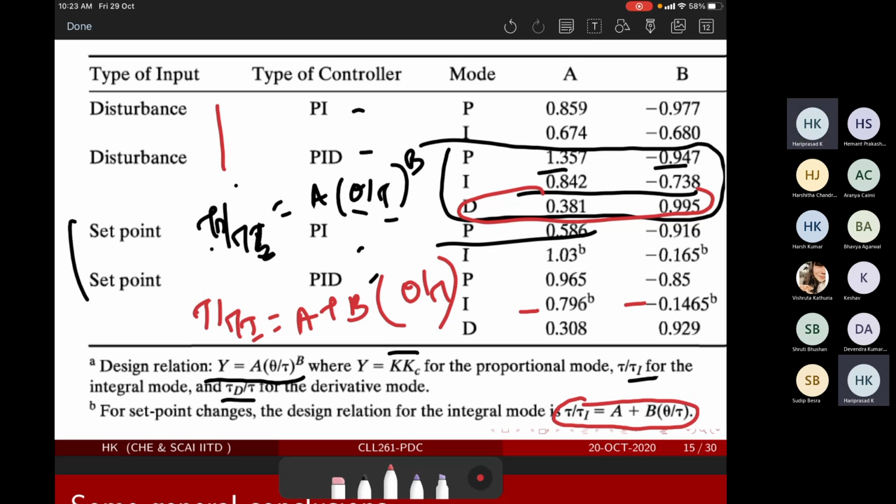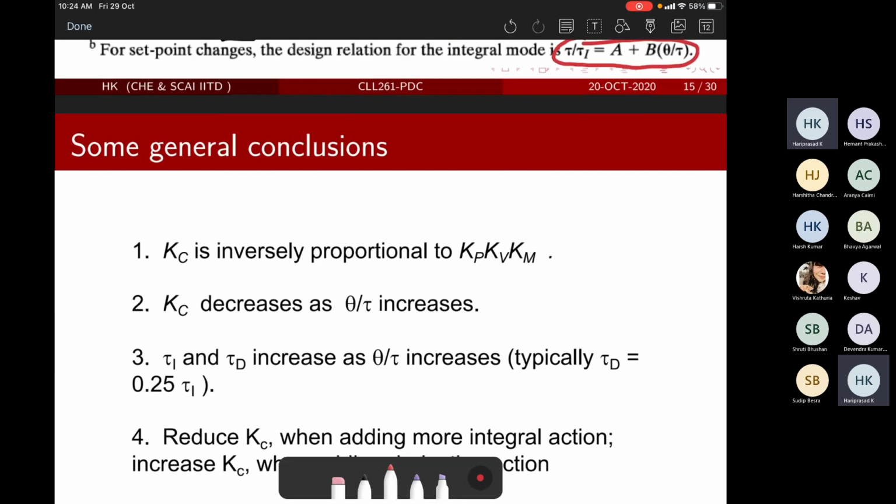You are not given the model, but they have told you the approximate time constant, approximate gain, and approximate delay of the process. But these don't help you understand the model structure, because the model can be first order, second order, third order, who knows. So you cannot use either direct synthesis or IMC, or any field experiment based approaches, which we are going to see next. So this is a middle ground. Let's start with this and see whether it works.